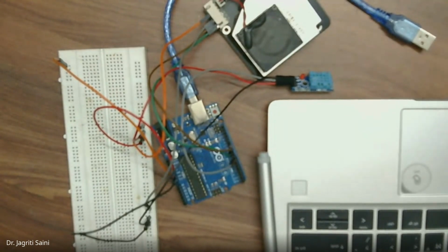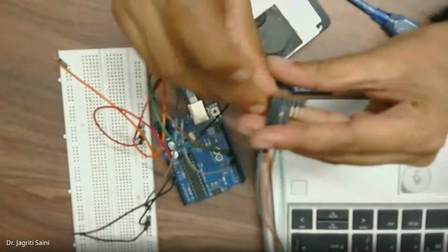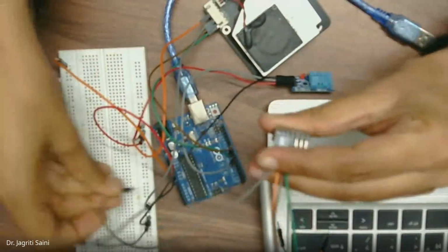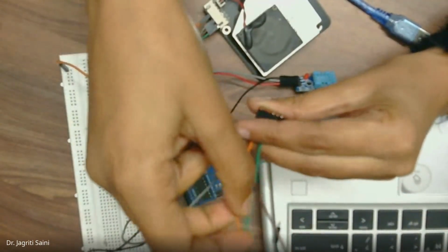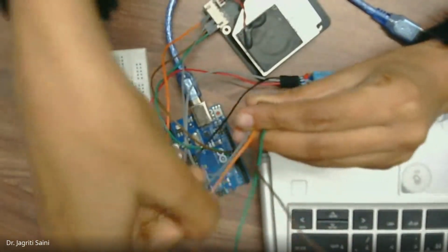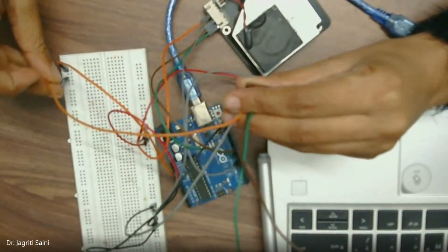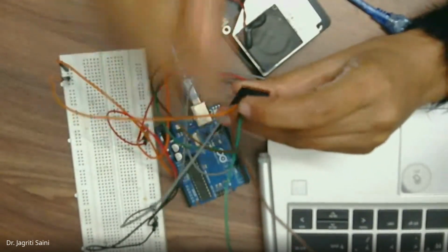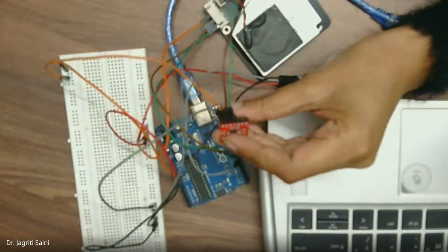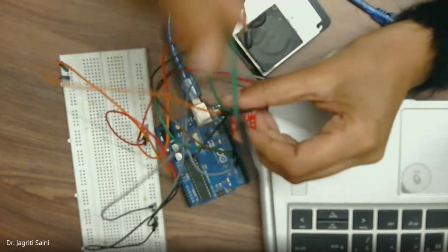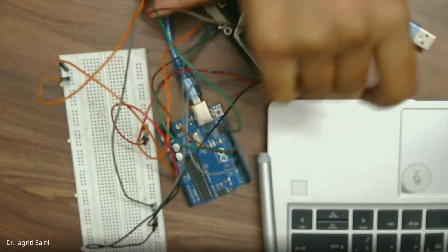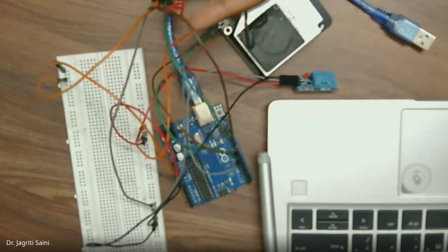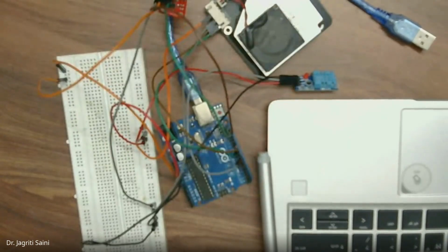Similarly, I have this CCS sensor. First, I'll be connecting its ground terminal right here. And then I have 3.3 volt. This orange wire I'll be taking to the 3.3 volt section on the other side of my breadboard. After this, we have SDA and SCL pins. The SCL, this green one, I'll take to the SCL, that is the last pin of my digital port. And the second last is SDA that I can use from here. Otherwise, you can use it on the analog port also. The last pins from there will work as well.